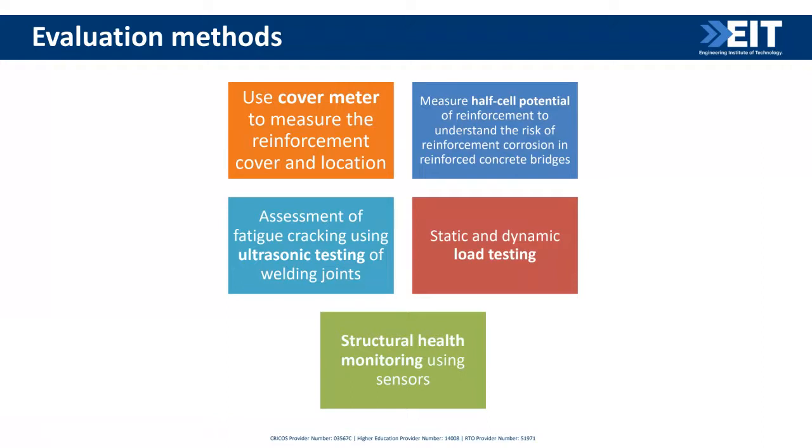But even with the current ones, for example, if the idea is to measure the reinforcement, we have the cover meter. If the problem is more about corrosion, the most traditional one is the half cell potential, and it depends on the type of problem you have in your structural element.